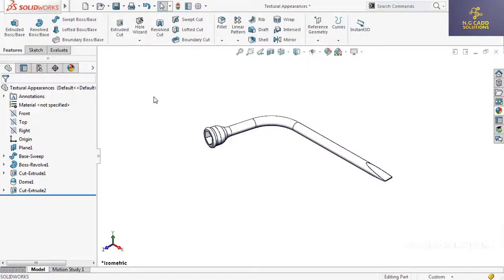You can think of it as a wallpaper, where, when applied, a 2D texture appears to be shrink-wrapped around a 3D model. Unlike procedural appearances, applying textural appearances is a two-step process. That is, besides selecting an appearance, it requires mapping in order for the two-dimensional image to properly fit. For example, during application, a textural appearance is stretched, shrunk, rotated, or reoriented to make it fit onto the surface. The material's pattern is also repeated as many times as necessary to cover the entire surface.